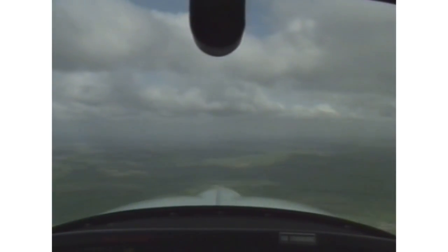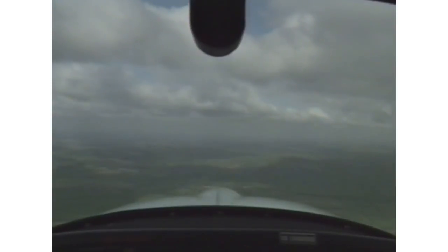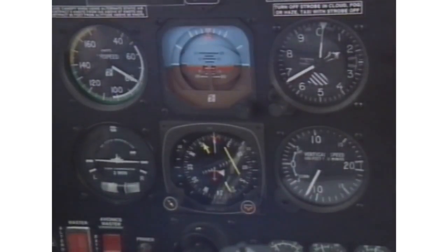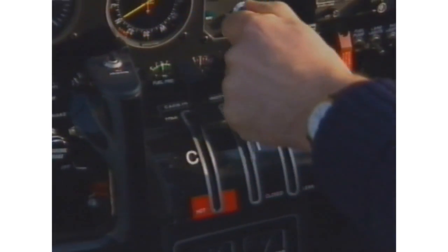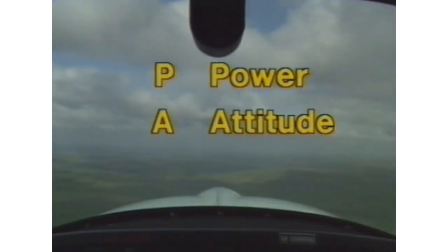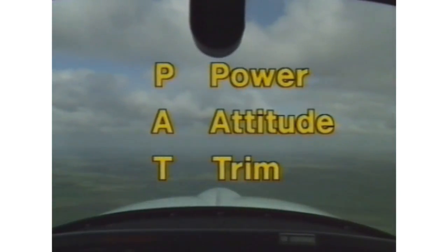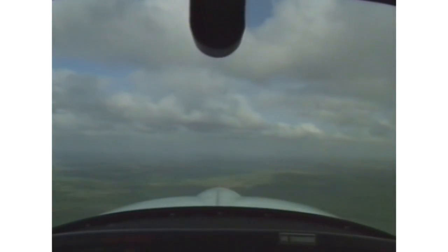We're now going to level off at 1500 feet. So, within 200 feet of the required altitude, carburetor air to cold, 100 feet to go, smoothly reapply power and reselect the known level flight attitude. And there we have it, see the new, or rather the old position of the horizon back in the windscreen.